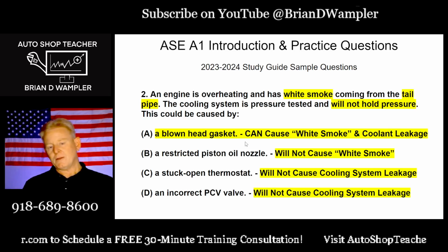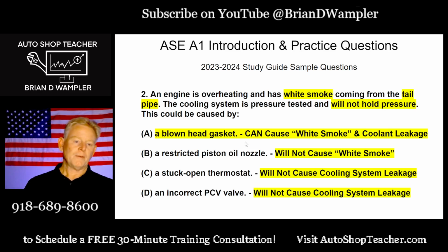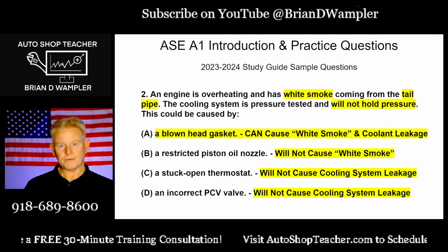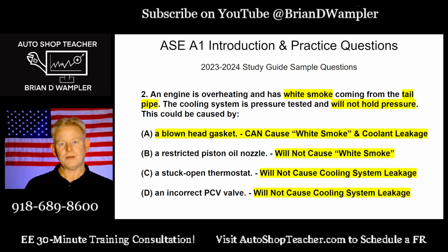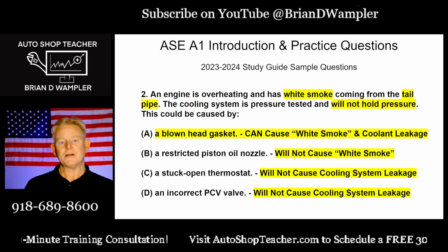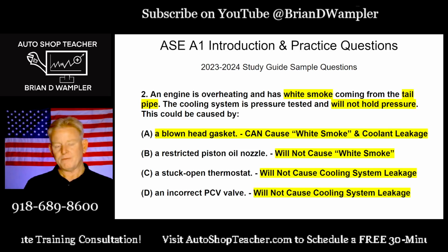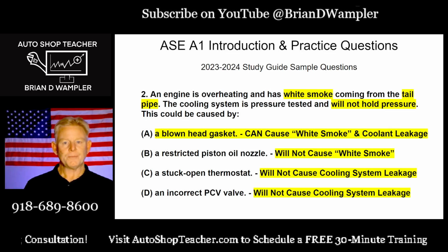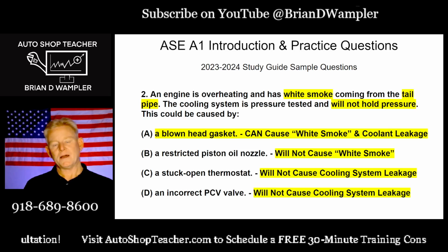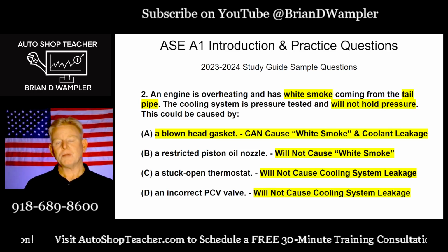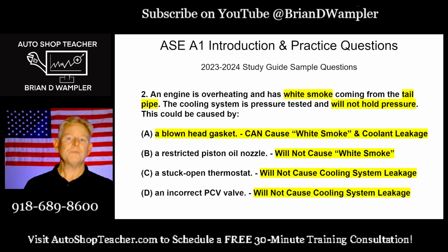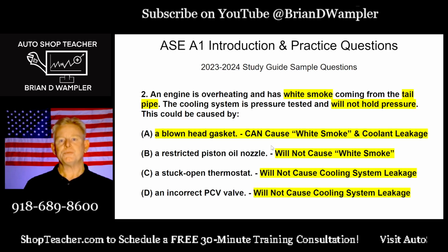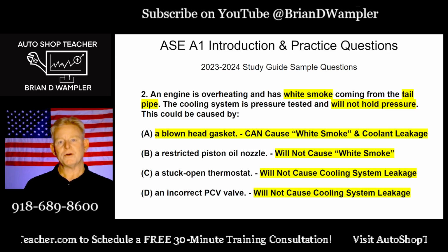One of the other types of smoke that we can talk about is black smoke. Black smoke is typically from unburned fuel. So we have too much fuel entering the cylinder, being compressed, being ignited, but part of the fuel is only partially burning, so it's being left in a carbonized state, if you will, that black color, and then being exited through the exhaust system. So black smoke we generally associate with too much fuel or a rich condition. And then we have what most call blue smoke. And blue smoke is when we're burning oil.